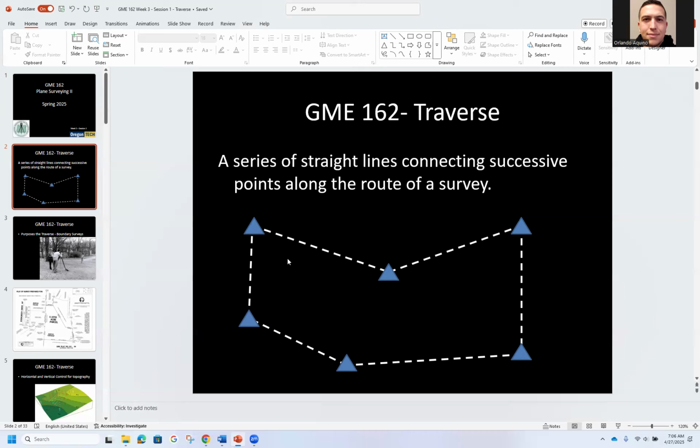Let's say we're working on a construction site through this area inside here. Well, when we run through that adjustment and get the misclosure down to basically 0, these become fixed points, immovable, right? We cannot move these points anymore. Once we run through the calculations, figure out our misclosure, and get the misclosure ratio to 1 in 10,000, that becomes the new control for that project.